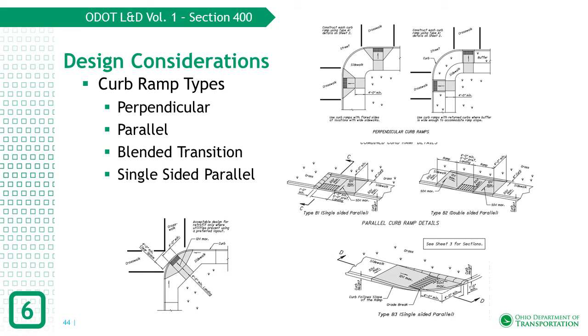Check the height of your curb if you're retrofitting curb ramps into an existing corridor. A curb height that is taller or shorter than the standard 6 inches will influence the length of the ramp to meet the ProWAG requirements for slope.